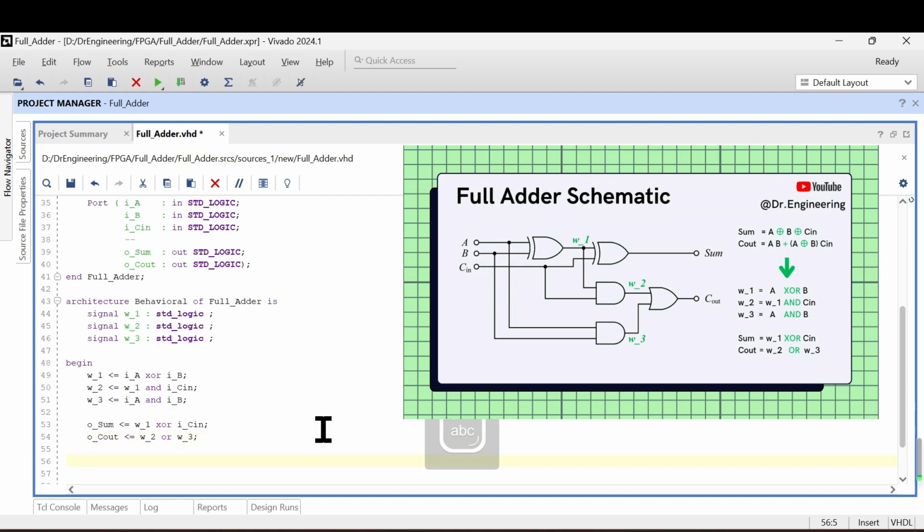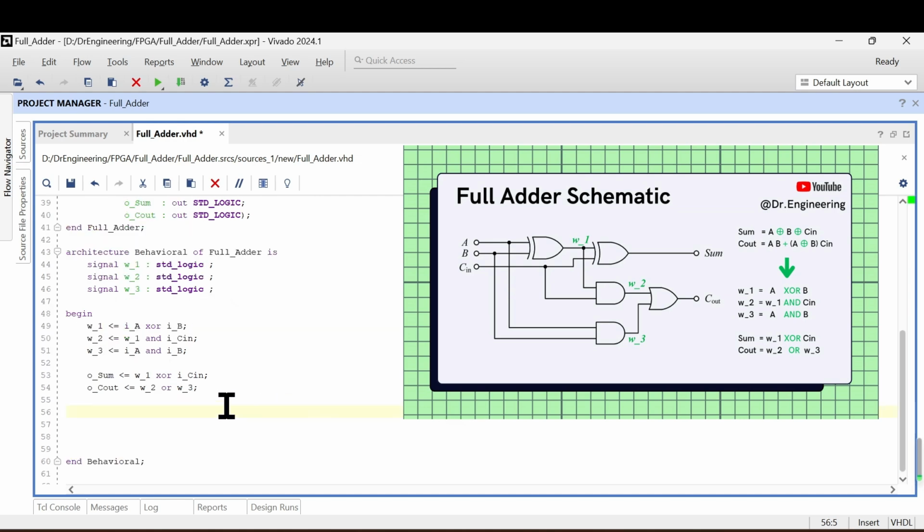You could also write out the final equation to directly describe the relationship between the inputs and outputs, but if the circuit doesn't behave as expected during simulation, debugging becomes challenging. A single long equation makes it harder to track down the issue. When we load the circuit onto an FPGA, all ports are connected based on our design as soon as power is supplied. So, both approaches, using intermediate variables or long equations, will have the same efficiency and behavior in real hardware.